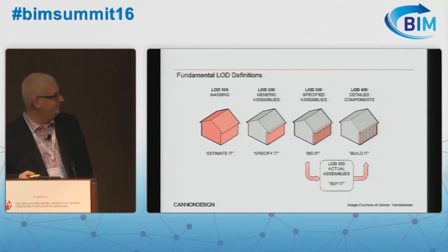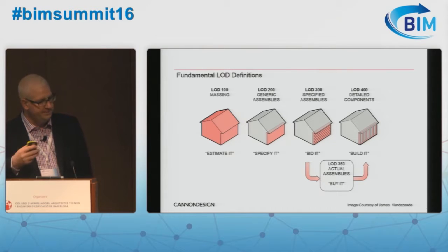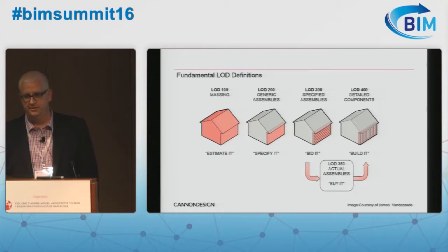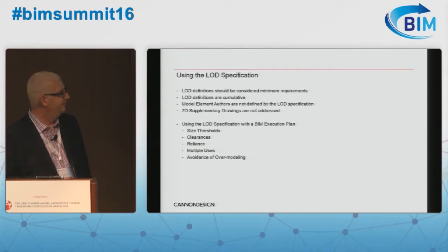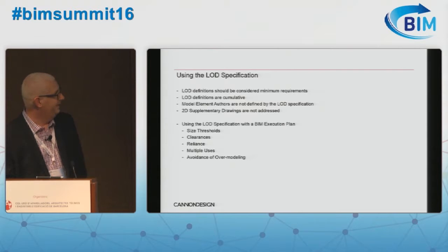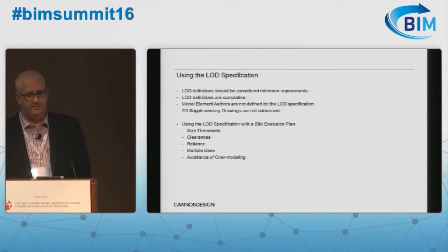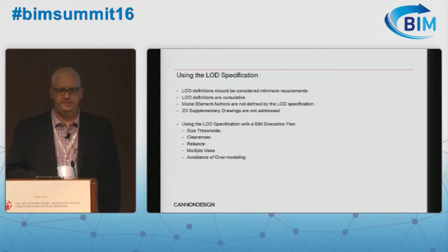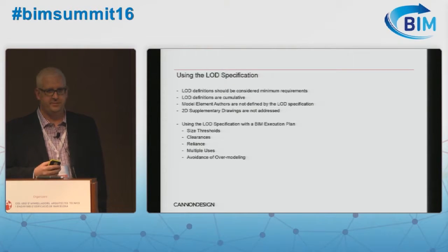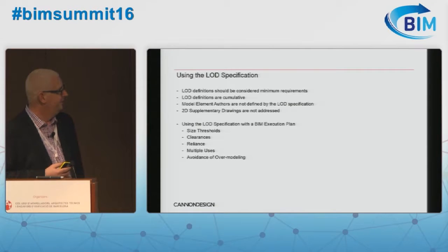This is a good way to really start to capture that information and talk about how we move from an estimate it, specify it, bid it, buy it, build it approach to using those different LOD benchmarks and definitions that are in place. A couple other items to know about the LOD specification is that it's a minimum requirement. Those levels of progression are cumulative. They add on to one another. You can't get to 200 or you can't get to 300 without meeting the expectations of 200.